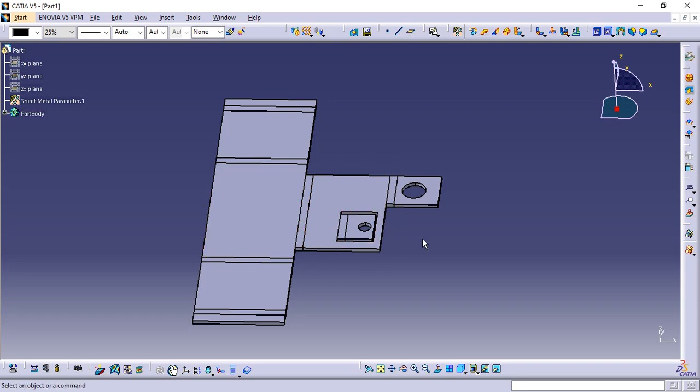So after creating your 3D model, if you are not able to make this flattened portion, then the manufacturing process won't work. Your design will have some errors. So that's why you need to design the sheet metal part in a way that you can unbend or flatten every face of this sheet metal. You have to design likewise. That is the one thing you have to keep in your mind.